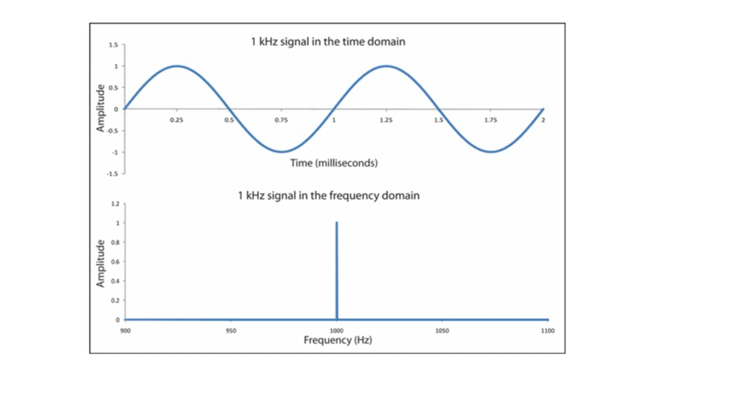Now here for the discussion purpose we are going to consider the Fourier analysis of a stationary signal composed of sinusoidal components here. So here we assume that the parameters that characterize the sinusoidal components, like the amplitudes, frequency and phase, are not changing with the time. So that is why we are talking about the stationarity of the signal for the sinusoidal type here.